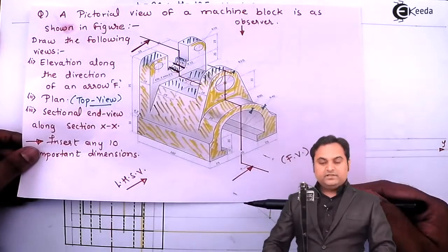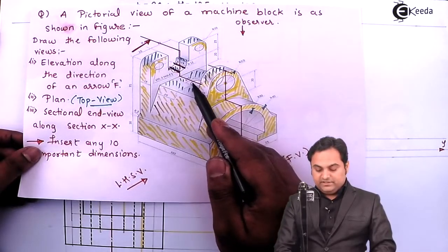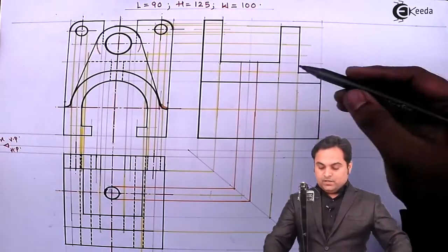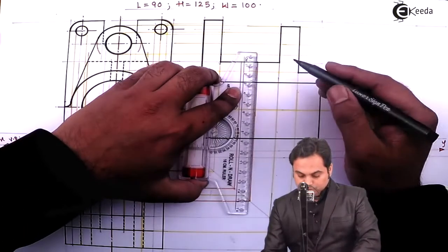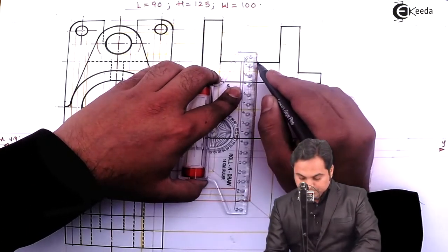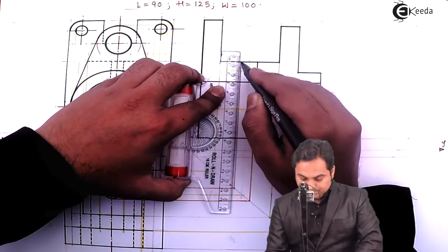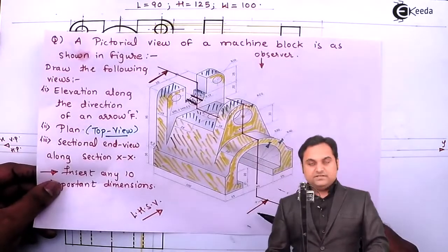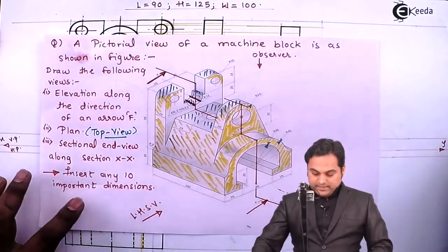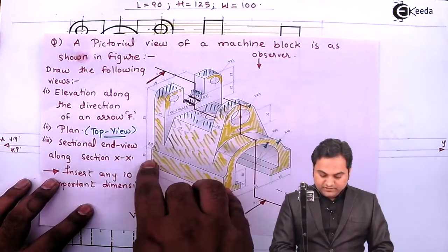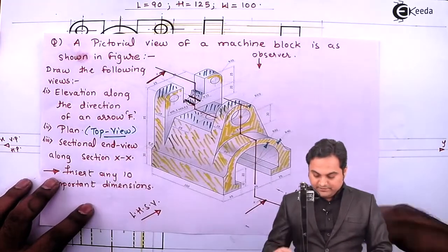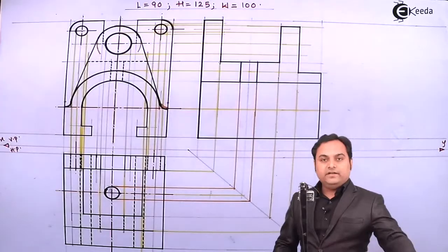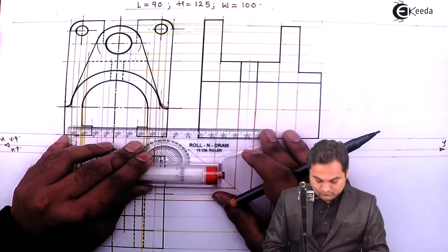Next, when the cutting plane is passing, this circle is getting cut, that is, it will be seen as a rectangular surface. So I'll project it and make it dark. Then when the cutting plane passes, as this front portion is removed, that is this rectangle of 30 mm height, then this small rectangle would be visible. So I'll get its height from the front view.